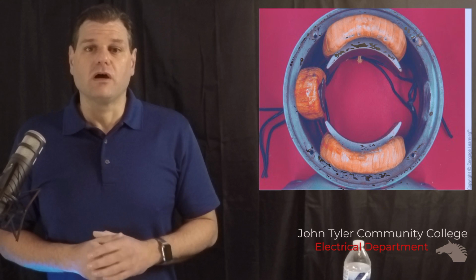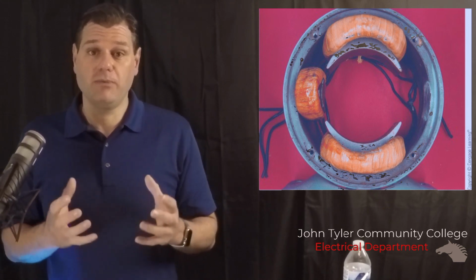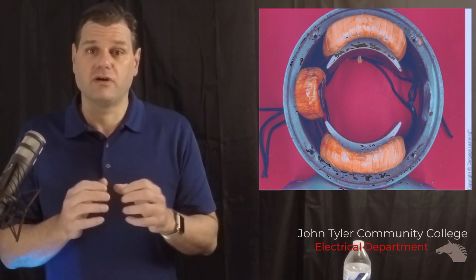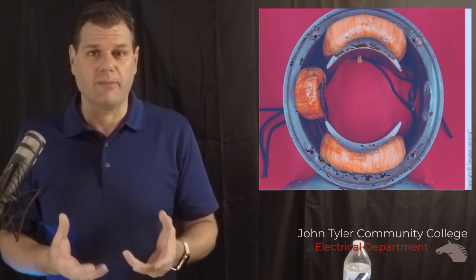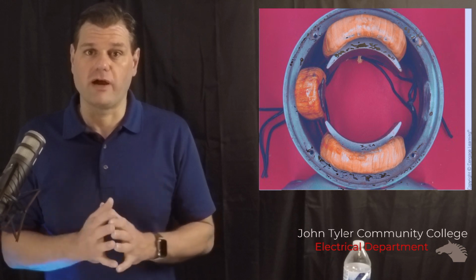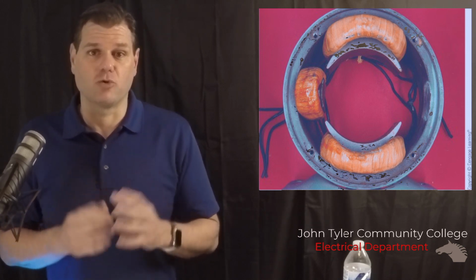All right. You can see the field windings here. They're wrapped in this epoxy tape, and this gives you a very safe skin almost over the coils, so they don't get damaged. They don't get dirt and grease inside the coils themselves, which would short them out. So this keeps it nice and safe, and the magnetic field has no problem going through.